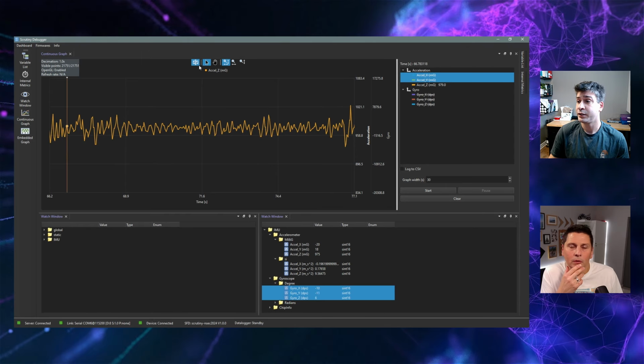and we see here that if we start looking at the points, if we look at the time closely, we'll see that the sampling rate is not stable because it depends on the scheduler of the OS running the server and the bandwidth available. So it's good to have a real-time feel, but if you have a problem, say you have an error bit that comes on at some point and you want to catch that, that's not the right tool, because your bit may pass from 0 to 1 between two samples, and you miss what really happened.